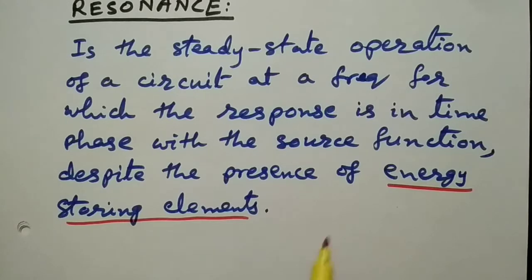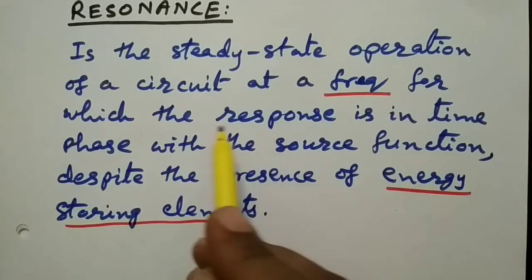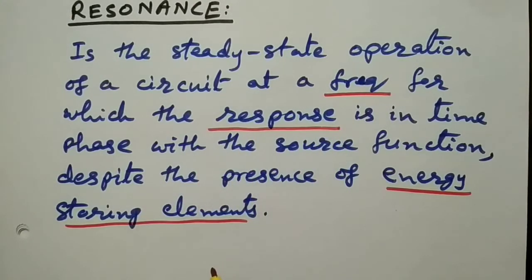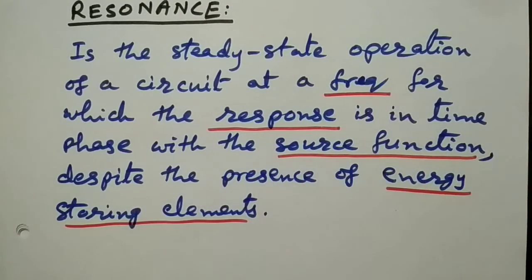So the definition states that if in an electrical circuit the energy storing elements, that means inductor and capacitors, are present, then at a particular frequency the response of the circuit, here response means the current, is in time phase with the source function. The source function means the supply voltage. So in simple words,